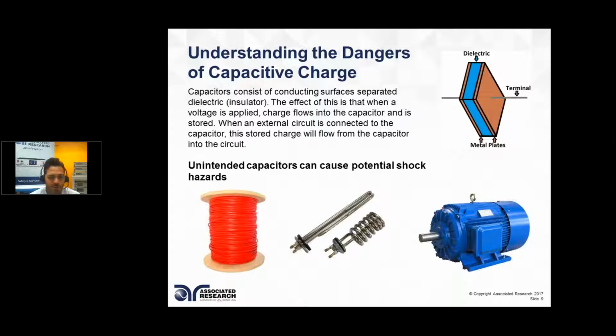Another thing is what's called a hot stick, or a discharging stick, where you just kind of short out the cap, and now you've discharged that charge through the stick to ground. It's usually got a metal piece that's a wire that goes directly to ground. So now you've let that current go directly to ground, and now you're fine. You've discharged your DUT. So those are a few of the steps you could take to make sure you don't have charged heating elements or motors or spools of wires sitting around your warehouse, where they can become hazardous situations.